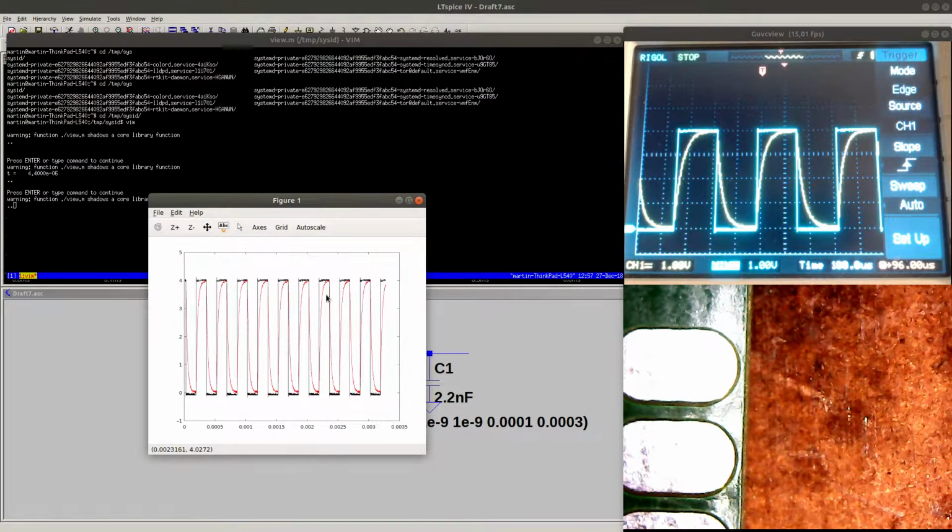So this is the signal that is captured from the scope, which you can see on the picture as well. It actually captures a much longer span of the signal, probably due to how the memory in the scope is set up. So when I do the transfer of the waveform, I get a much longer waveform. But this is workable. So we have stimulated the system with this square wave, and we got as the system response this filtered wave, and the equation of the system is the transfer function from this input to this output.